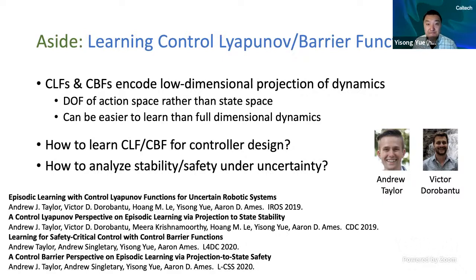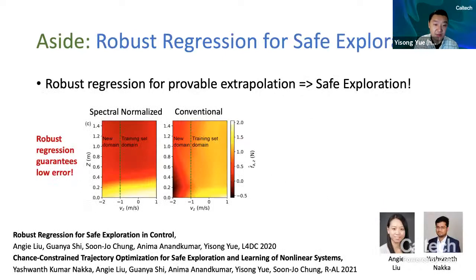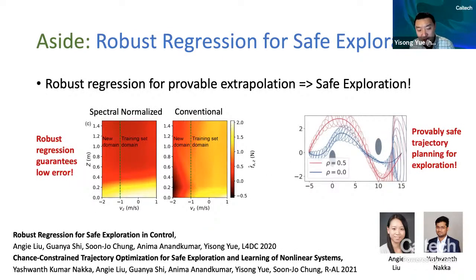For instance, if you want to do high-speed drone landing, just to give one example, and agile control close to the ground, as far as I know, the way you want to do that is you fly a little bit slow, then you train your neural net, and then you compute a new neural net residual model of the ground effect or any boundary conditions. Then you fly faster, collect that data, train, and collect more data. You fly even faster. That's called episodic learning, and it's a very different way of doing learning than online or on-the-fly learning, which is effectively what adaptive control is. So I think they're suitable for different situations. In this case, I have a hard time imagining that you can actually adapt on the fly in a single shot.